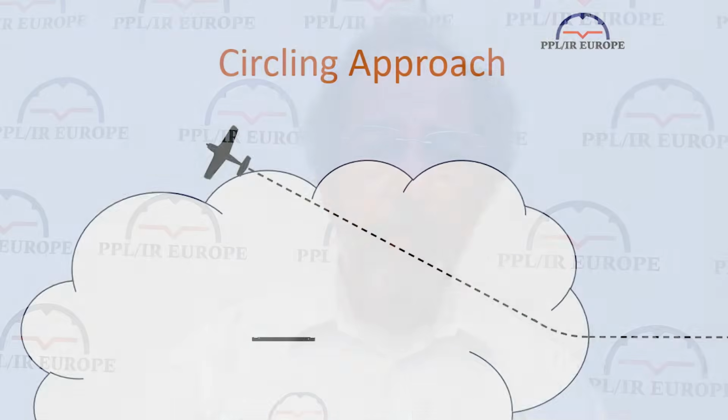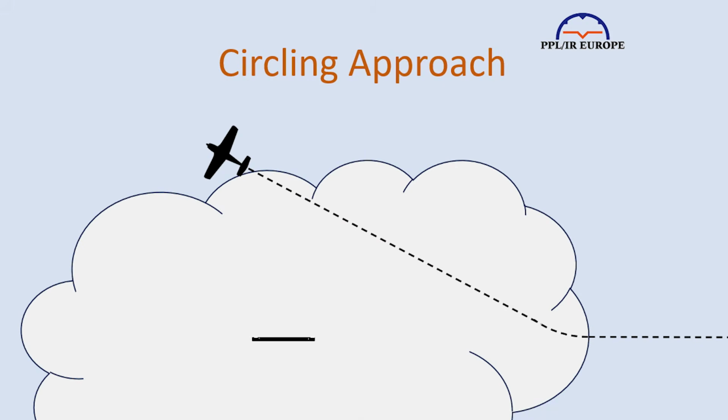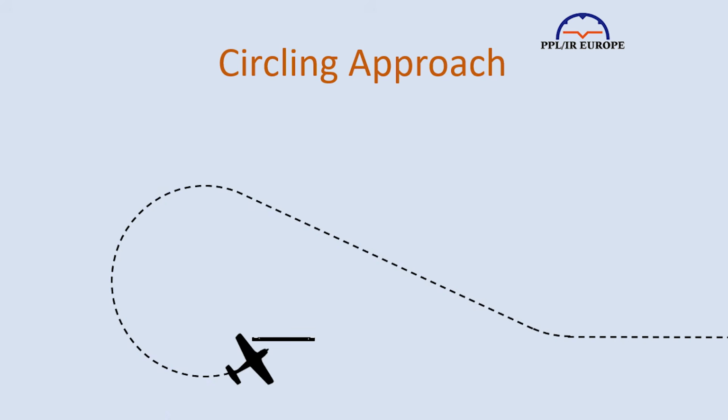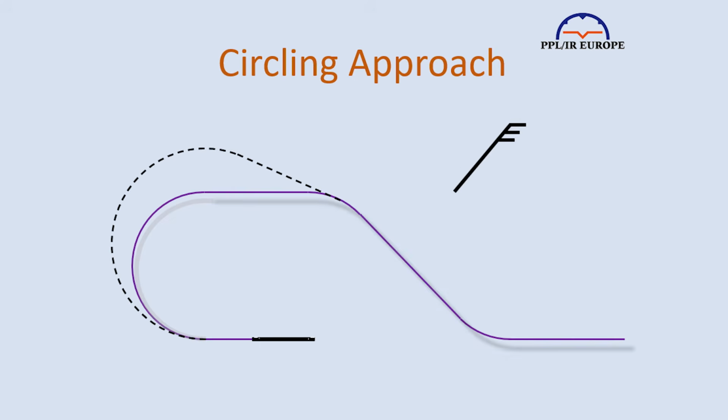Pilots should bear in mind wind drift when selecting circling tracks and stay within the protected area and inside the runway. Drift away from the runway can result in losing the runway in the murk, and drift towards the runway can result in overshooting the centreline and potentially unstable and unsafe manoeuvring on final. This usually means doubling the drift correction outbound to allow for drift in the inbound turn. If that carries a risk of losing the runway, you might consider a diversion to a runway with less crosswind. You shouldn't descend below the MDA until you can see the threshold and are in a position to make a normal landing on the intended runway.